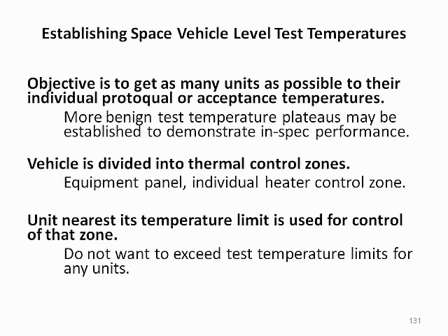We will now take a moment to discuss how target temperatures are established for spacecraft-level tests. This is not as straightforward a process for spacecraft as it is for individual unit tests. When testing at the spacecraft level, the objective is to get as many units as possible to their individual protoflight or acceptance temperatures, with more benign test temperature plateaus sometimes established to demonstrate in-spec performance.